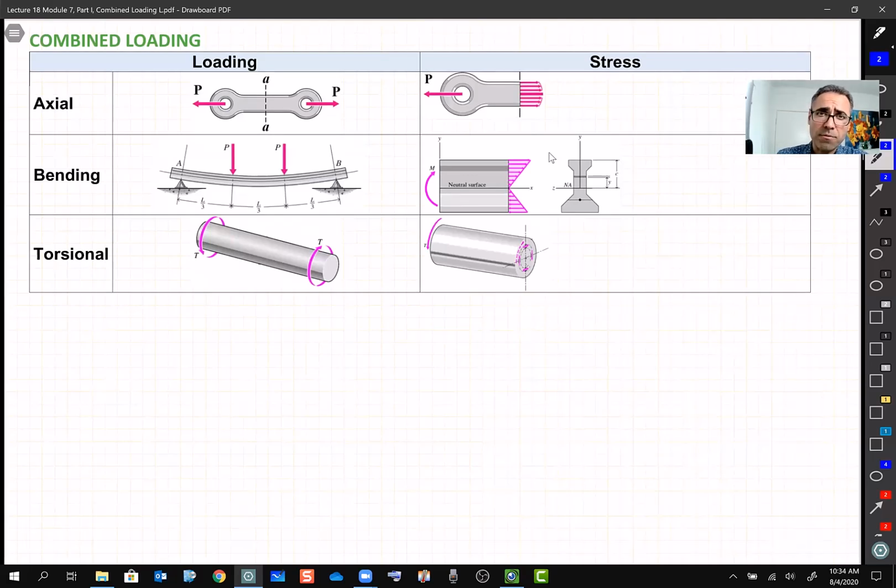The third type of stress that we just learned was torsional stress. We show it by tau. It is tau because, unlike the previous two scenarios, where we have stresses normal to the plane, in case number one the stress is normal to the cross section, and the second one is also normal to the cross section. But for torsion, we learned the example of discs sliding on top of each other. It is on the surface. It is more like friction, and that's why it is tau. It is a shearing stress.